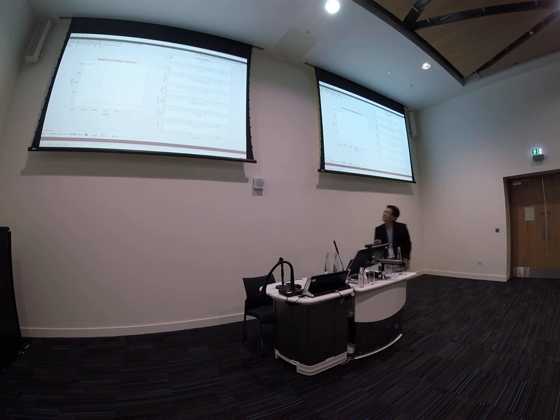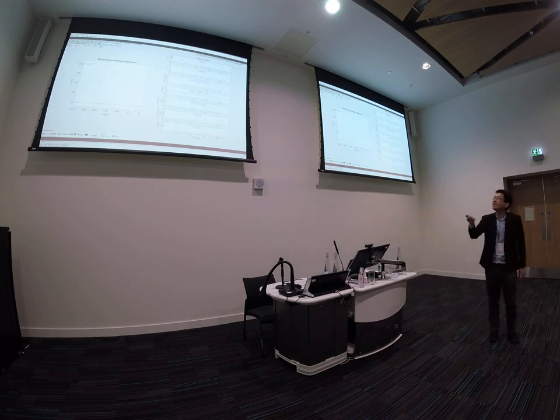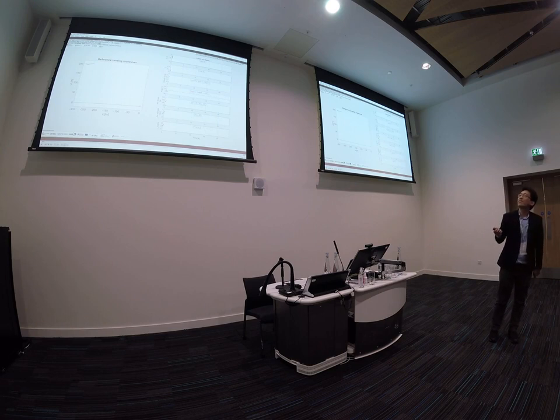So I will explain this. This is the longitudinal plane, the x and the minus z, because z is pointing down, so I have to put minus z. The control input delta E is the elevator deflection here. Delta T is the thrust force.